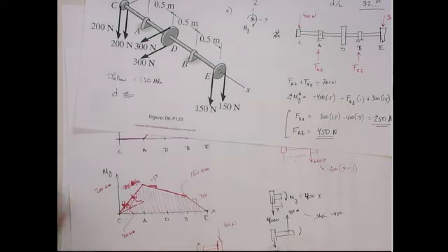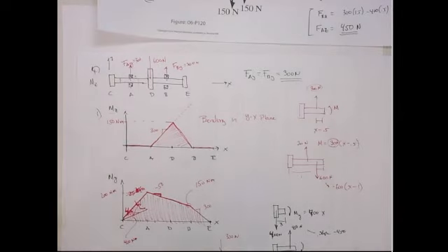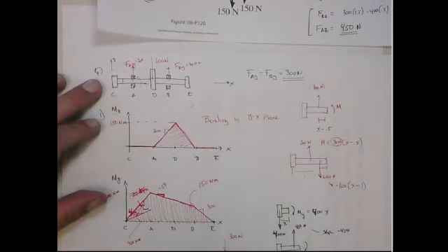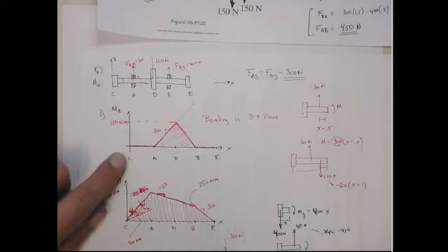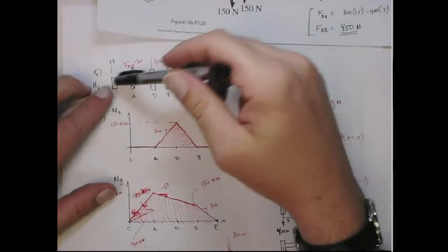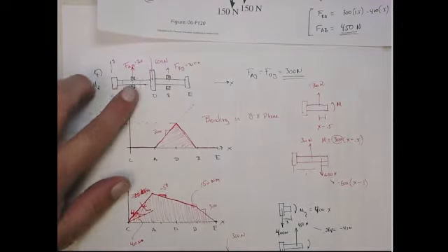I should probably say that again. I've done plenty of these examples where I explicitly draw the free body diagrams like that, and you can check that as well. But what I'm saying is when you're doing these and you have these point forces, it's kind of easy to directly or graphically construct the moment diagram, right? The change in the slope of the moment diagram is going to be equal to the point force.